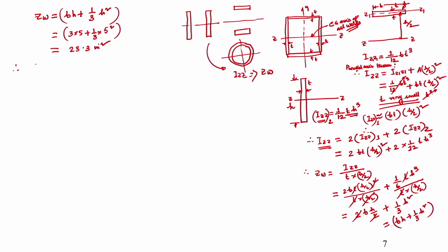Now, what are the other things required? Now, we need to find out what is Qx resultant. First of all, I will find Qx resultant, which will be due to force Px by Lw plus Mx divided by Zw. Always you should keep it in mind. Okay. And here Px is given as 4.91 and Lw is 16, and sorry, here it is not Mx, it is Mz actually.